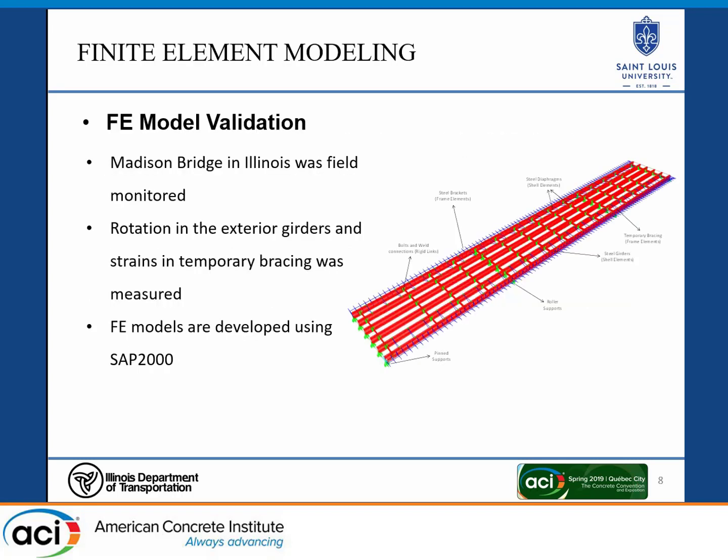What we did first was we had to use an FE model to do this, and so we validated by comparing to a bridge we studied in Madison County in Illinois. We field monitored this bridge and got actual field results from it. And then we modeled it in SAP 2000, our computer program at our university, and we were able to reconstruct it here as an entire bridge. We used frame elements for the formwork, and then shell elements to create the girders and the diaphragms, and rigid links to create the simulation of the bolts and welded connections.